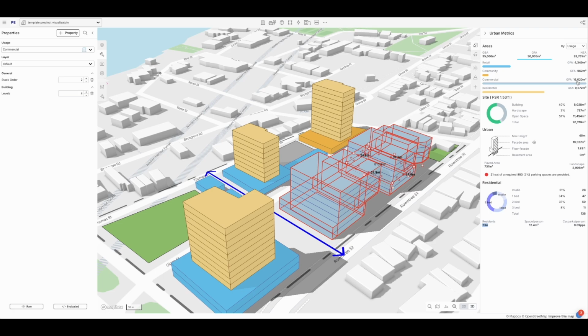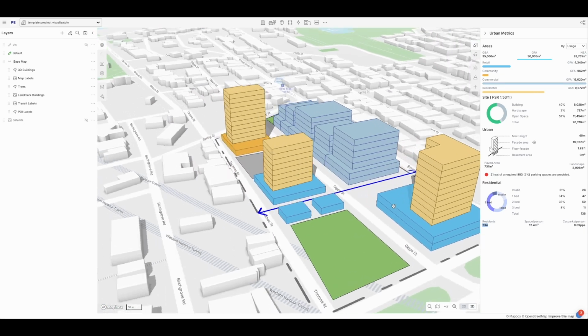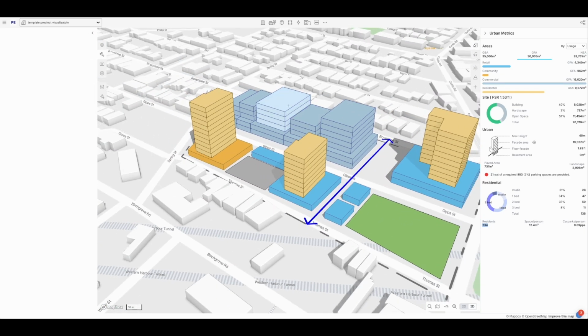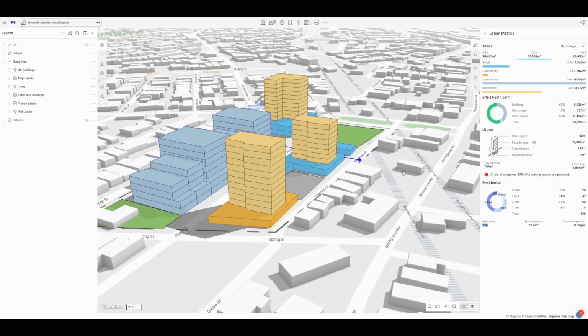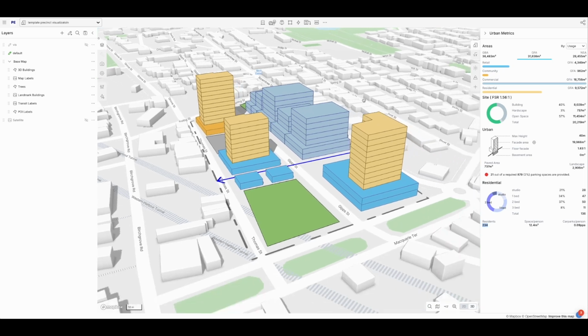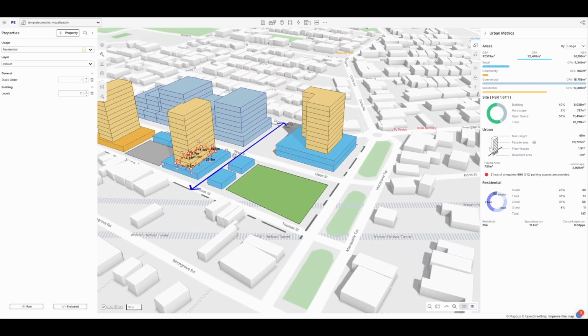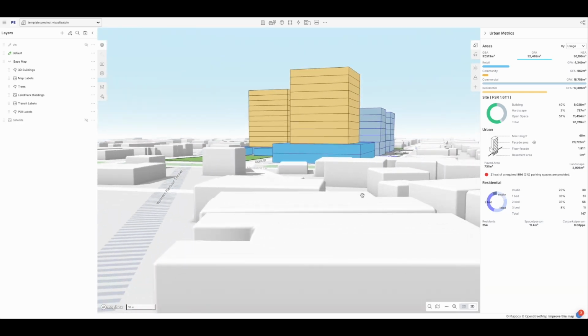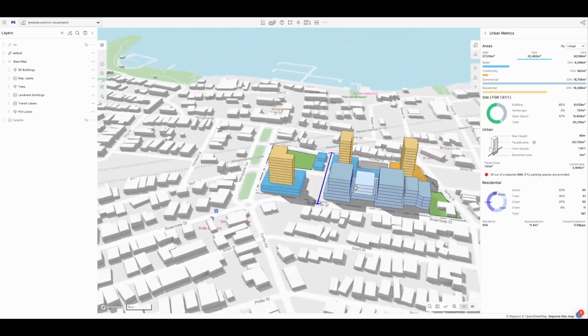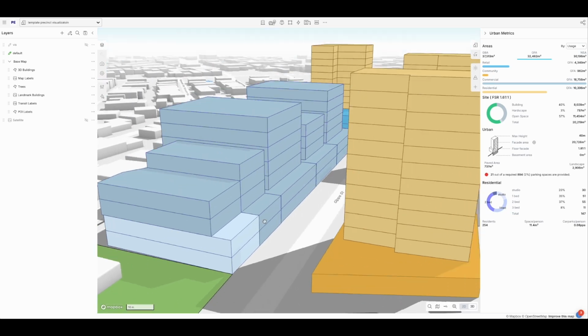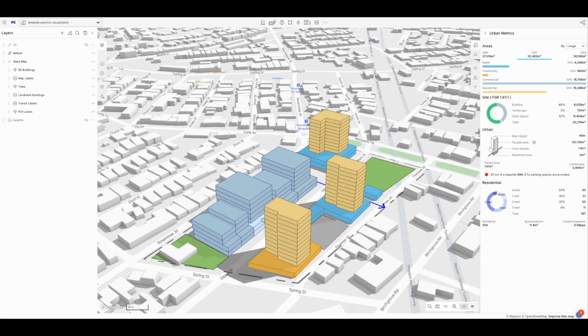Sorry, it's 1,600 if there's one every 10 square meters, otherwise it's 160. So let's say there's going to be 1,600. But all these simple calculations that Giraffe does for you out of the box are done at this level of fidelity. And I would say you don't need to go much further than this. This is enough for you to understand view impacts, solar impacts, to certainly talk about the bulk and scale and the feeling of the street. However, one can go a bit further, and I'll show you how one might.